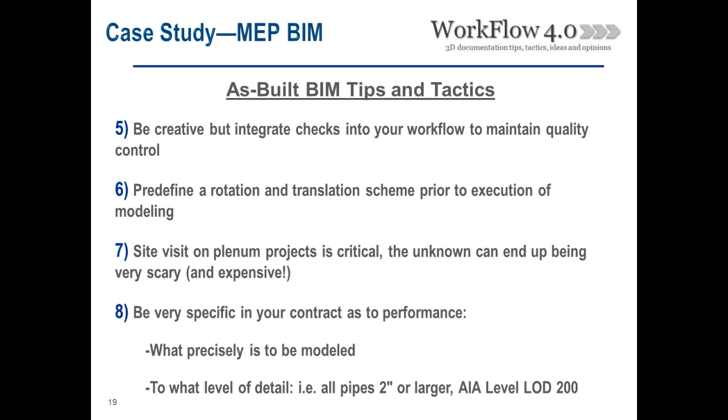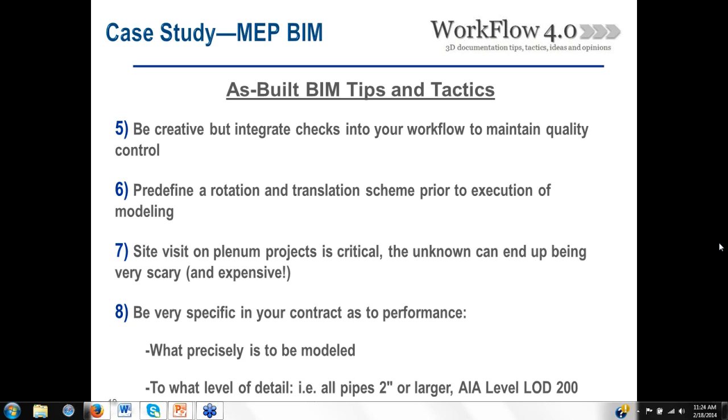A lot of software has things in there that, if you don't explore, you don't find them, or can be adapted in different ways. Always make sure that you have your game plan for the BIM model clear with the architects involved, so that you're not having to rotate and translate things after the project has been executed. And a lot of Revit families are not conducive to being moved once they've been placed.